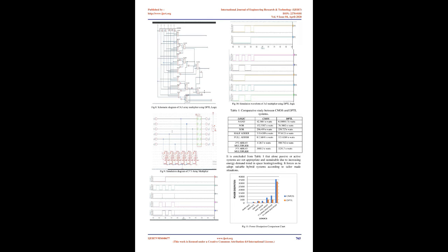4. Proposed architecture of array multiplier. The array multiplier is a digital combinational circuit that is used for multiplication of 2 binary numbers by employing an array of full adders and half adders. A basic multiplier can be divided into 3 sections: partial product generation, partial products addition, and final addition. This is a fast way of multiplying 2 numbers, since all it takes is the time for the signals to propagate through the gates that form the multiplication array.